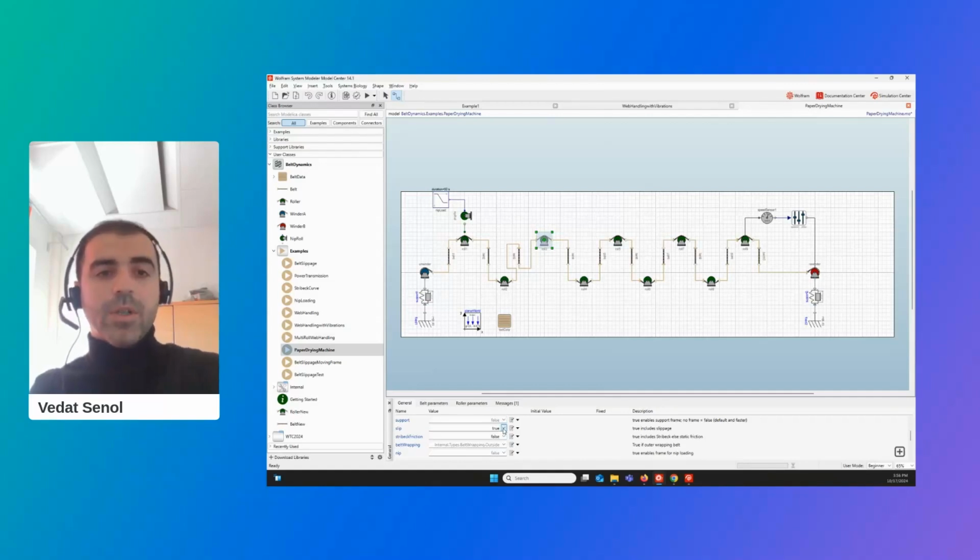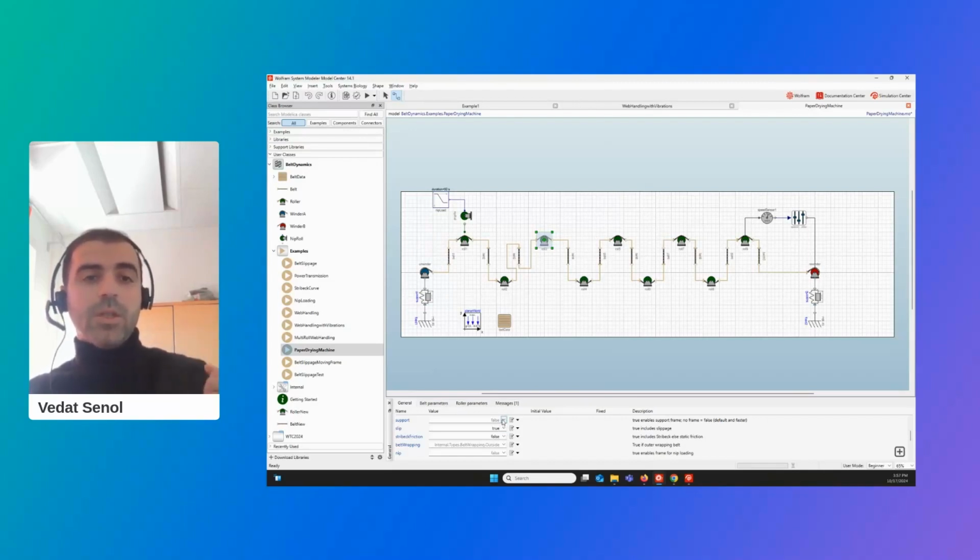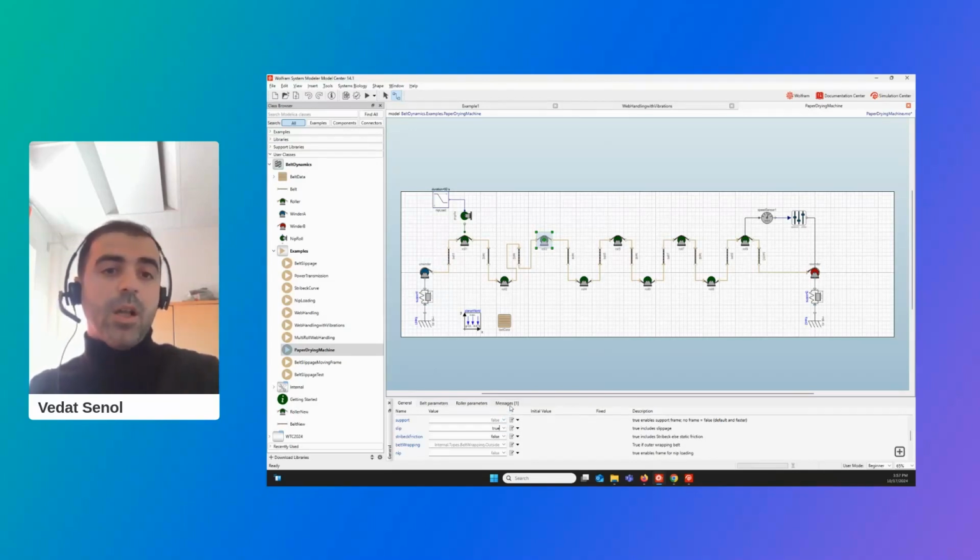And when it comes to friction models, we have two different models, one being the Coulomb friction, in which until we reach that value, the system starts slipping. And the other one is the Stribeck friction, in which we have a really well-defined velocity-dependent and viscous dynamic friction model. So it is all up to what our expectation is, what type of fidelity we would like to get from the model.